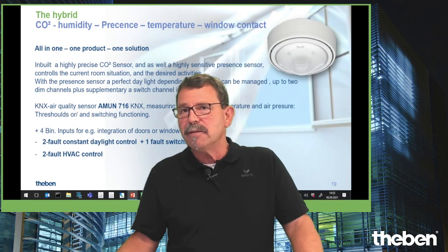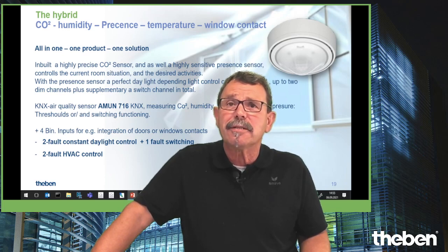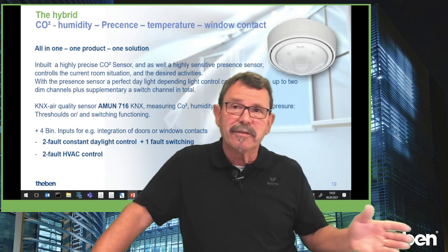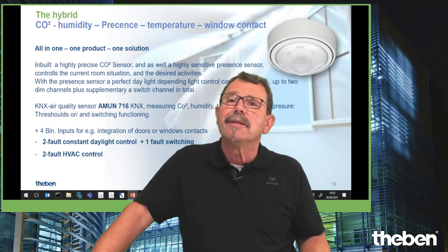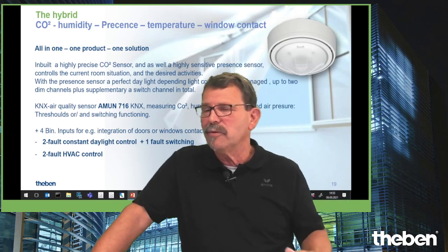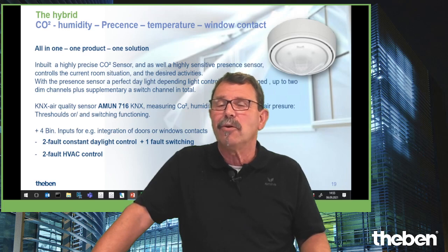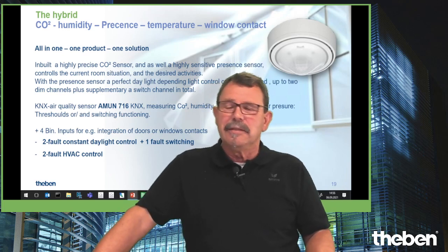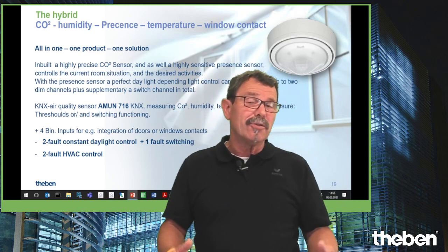It just requires a bus cabling, in terms of the wiring to this sensor, and with this single unit you can do light management and daylight control, for instance, highly efficiently. You can do the management for the CO2 or for the climate, because a temperature probe is inside as well. So, most simple to reinstall, to retrofit.